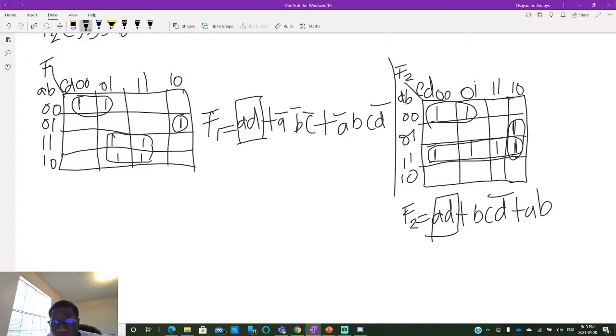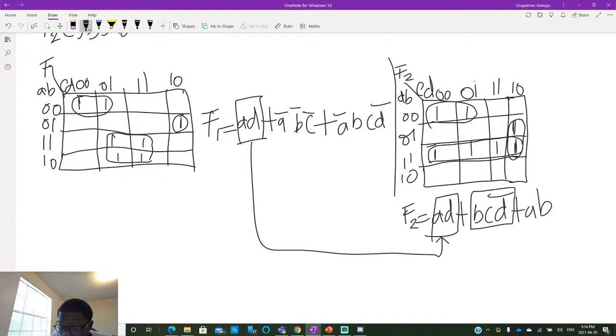Okay. So, as already mentioned before, these two terms can be shared, right? But an extra term can be shared as well, and that could reduce the number of three input AND gates that are used. In fact, you wouldn't even need a four input AND gate in this case because the term BCD bar can be shared between both systems. So for this circuit, you would only have to create BCD bar once, and then you would implement